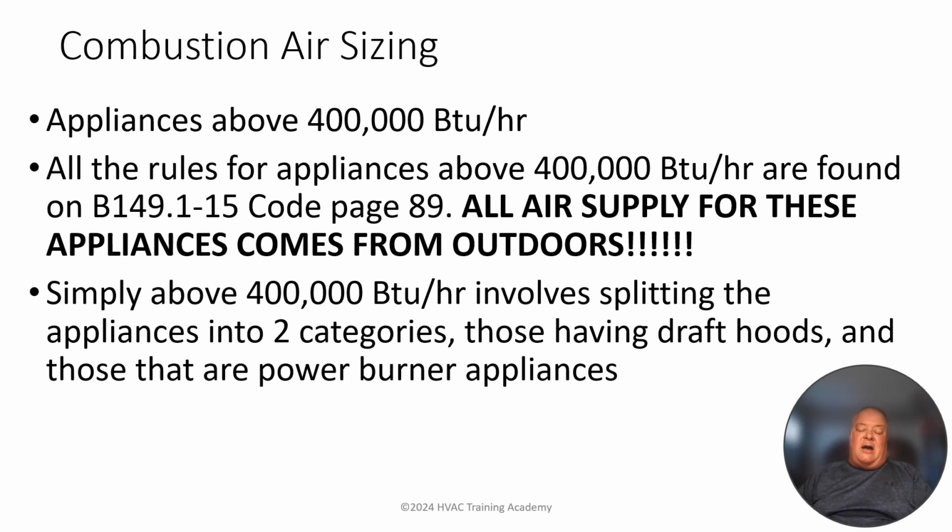So in this case, with a 60% free area grill, we divide by 0.6, and our new opening size is going to be 208.333 inches. In order to get 125 square inches of air through that grill, our opening now needs to be 208.333 inches squared. I just want to make sure you understand how to do that, because our friends at TSSA do like putting at least one of those questions on there with a grill size on it and telling you to calculate it.